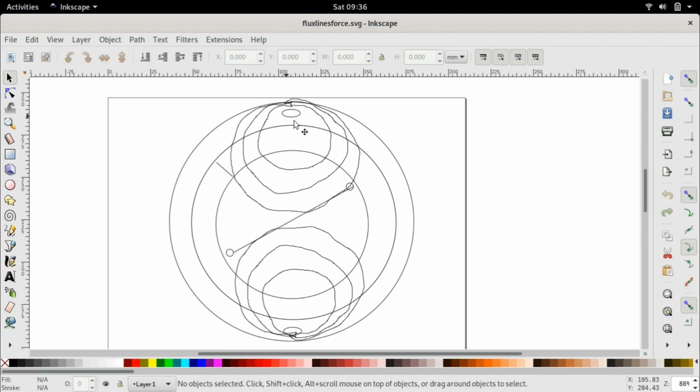The current in the stator conductors produces a magnetic field. You are applying an AC voltage, therefore an AC current will flow. This AC current produces an AC flux, which means it is a varying flux. When a varying flux is associated with another conductor, it induces an EMF. So this magnetic field produced by the stator will induce an EMF not only within the stator but also in the rotor, any conductor that it associates with.